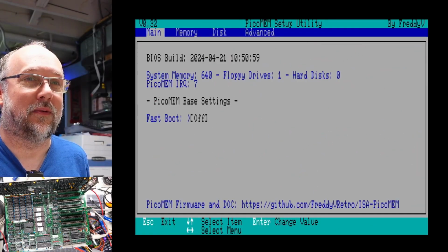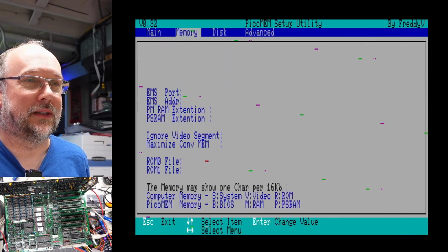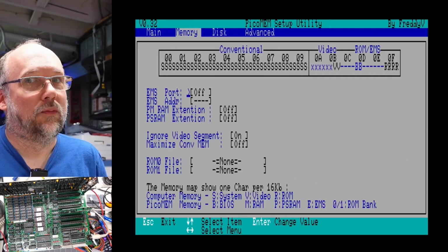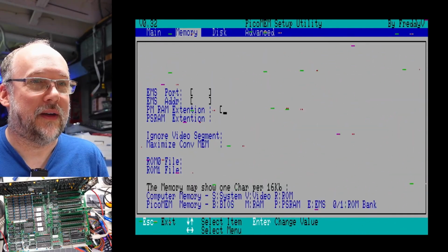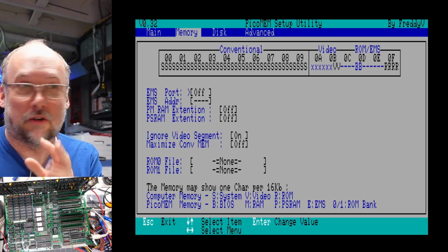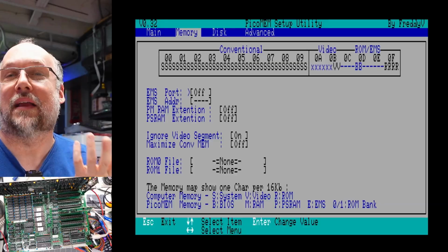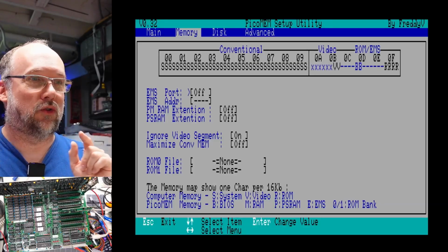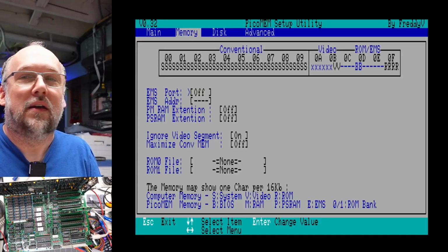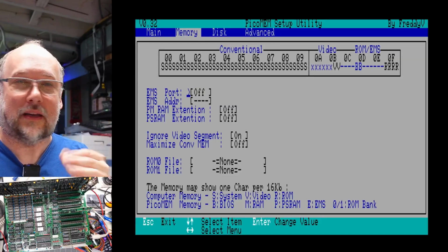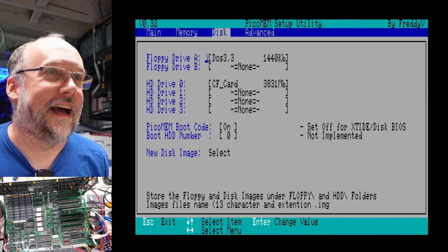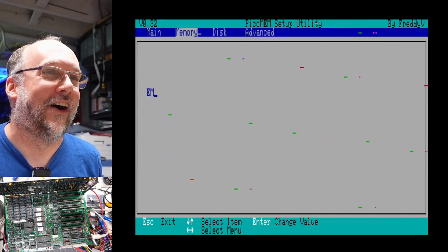And let's go to the setup of PicoDOS. Yeah, same thing, a little bit of snow here, because I'm assuming it was probably waiting for that signal as well. But I am guessing that 3.5 megahertz is actually a lot faster than the, what, 15 kilohertz or so that was happening on that signal originally, because that is the actual horizontal refresh rate, 15.6 kilohertz. So we're definitely having a speed up because it's not going to have to wait. It's going to still have to wait a little bit for that 3.57 megahertz. But yeah, it's not going to wait as long.